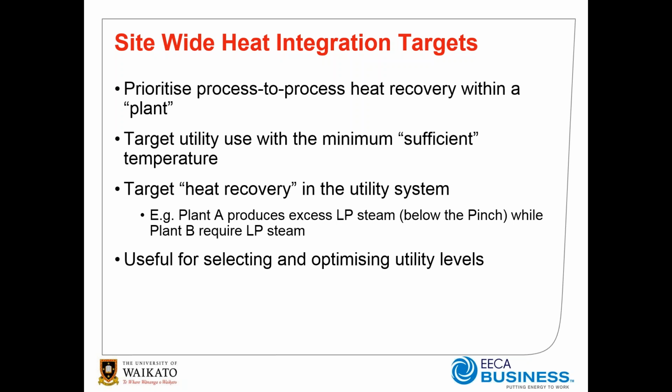And so there is a timing issue between when heat is available and when sinks of that heat, what needs heat, is also available, and they may not coincide. And so if we tend to focus on defined plants or zones where we use our engineering judgment to decide that these streams can be directly integrated and do tend to occur at the same time, then we prioritize heat recovery within those defined little zones.